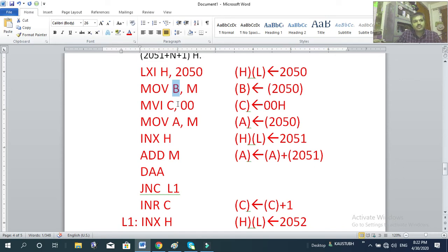Now see, in 8085 there is no instruction to say whether the count goes from 1 up to a particular value, say capital N equal to 5. But there are instructions to say whether a counter is decremented till 0 or not. So in 8085, a loop always counts down to 0. In a high level language, we initialize with 1 and go up to the maximum count, but here we start with the maximum count, say 5, then 5, 4, 3, 2, 1, 0, like that. So the counter will be register B, because B is now holding my capital N.